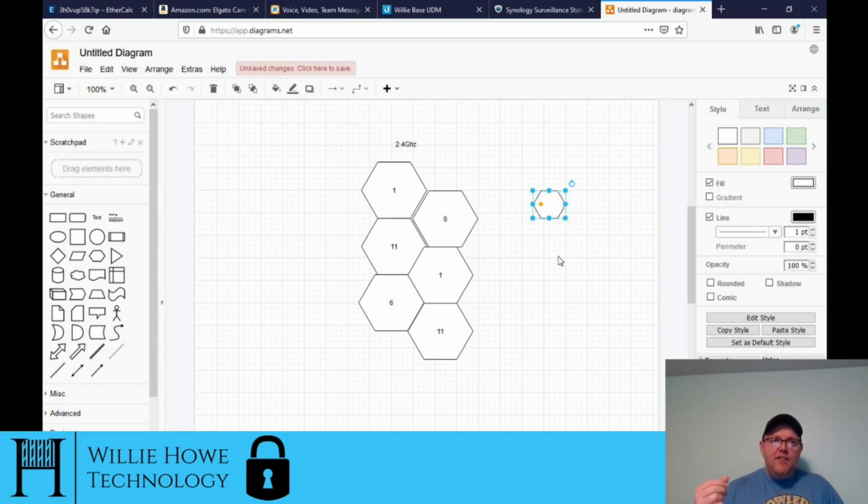If we don't have heavy canopy, then we might go with a 2.4 gigahertz solution, because the problem that we're running into now with 900 megahertz is SCADA systems, and all these new smart meters that they're installing on homes and businesses, all run in that 900 megahertz range. So even in the most rural areas, we can start running into in-band interference in the 900 megahertz range.